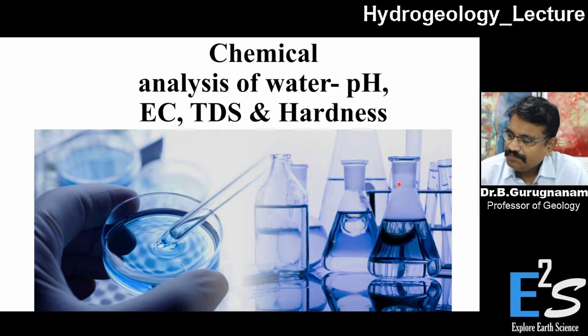The first step, to be done in the field itself, is the assessment of temperature-controlled pH, EC, and TDS. All these are very important parameters that have to be tested in the field, and then when you come back, even within 24 hours, if you do it, it is quite better to assess the quality of water.